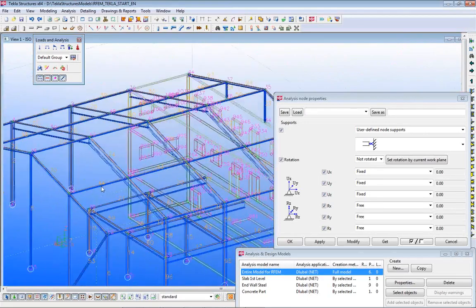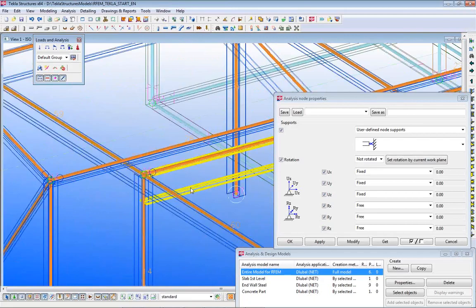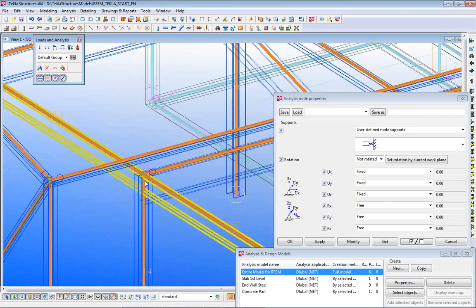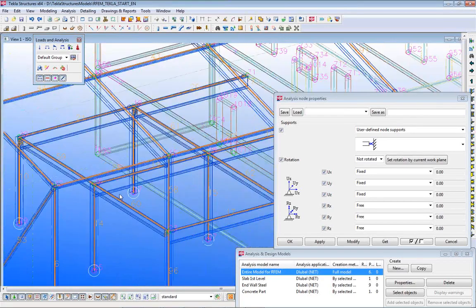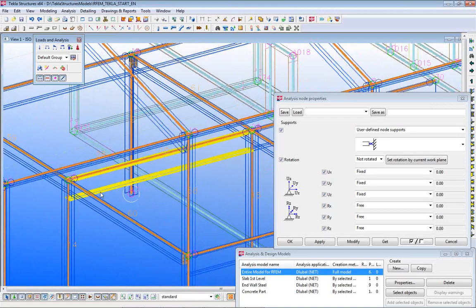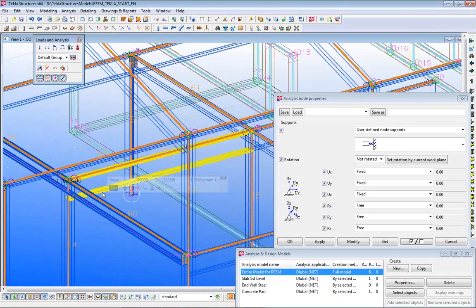I've made the model in such a way, for example, that those beams here are modeled as top of steel, and this analytical model lies in the center of the top flange. So it's one level. And important is when we update the sections later, that those sections, even if they change in the section, they should stay top of steel.